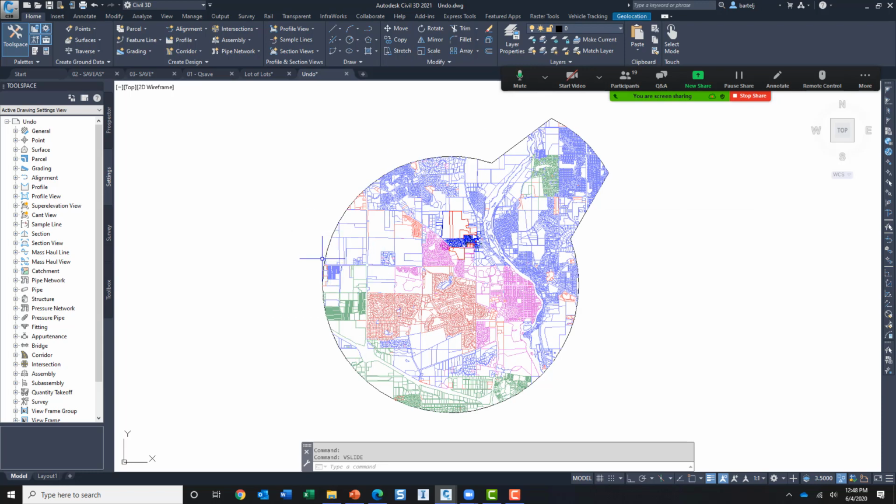What I'm using is another tool in the application that has literally been in the application since way back in, I dare say, the late 80s. It's called Make Slide and V Slide. What that does for us is if I wanted to capture the contents of my screen, just an image, I'm not creating a raster image, I'm not creating something that can be viewed outside of AutoCAD or Civil 3D. Instead, I'm just capturing the display.